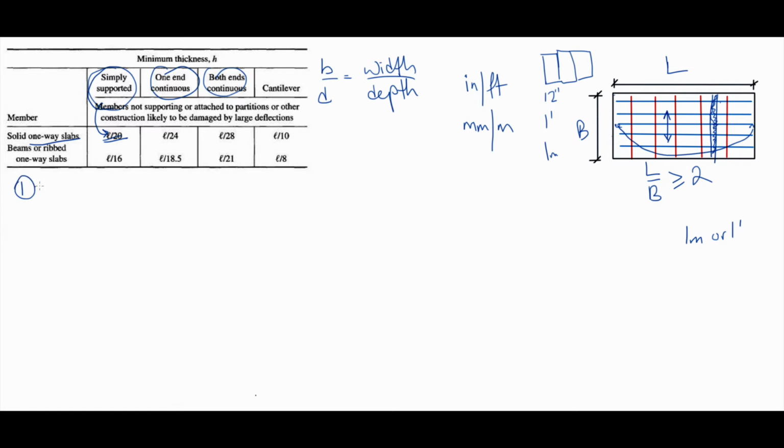In slabs, we have two types of reinforcement. We have the main one, which is the one that is taking the load, the main rebar or reinforcement, and the other one is shrinkage and temperature reinforcement. Talking about the main reinforcement, the area of steel is calculated by the area of the bar divided by the spacing, but multiplied by 1 foot, which is 12 inch. Everything will be clear when you start designing or calculating.